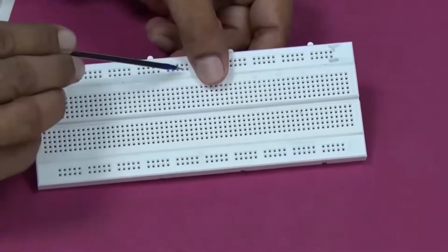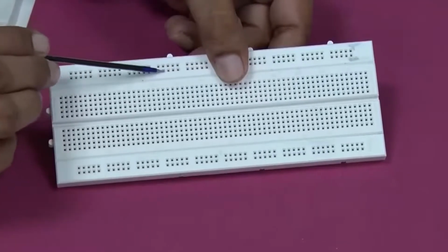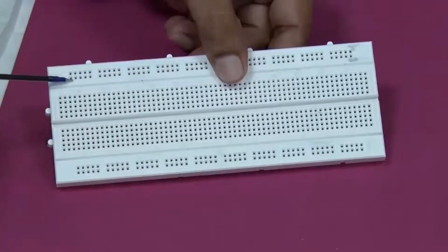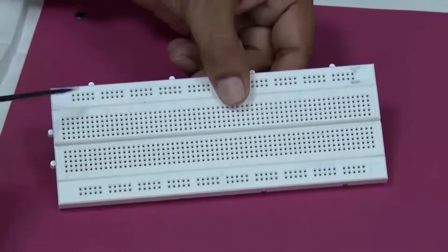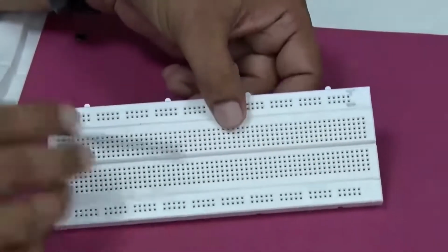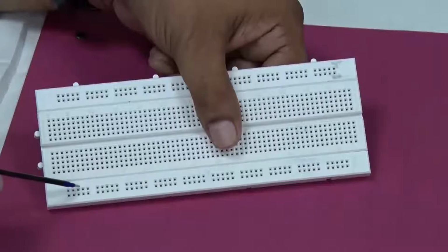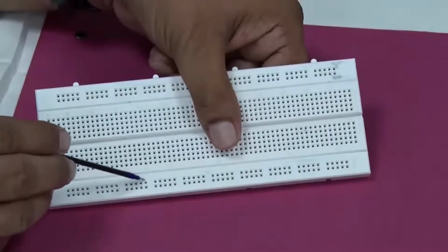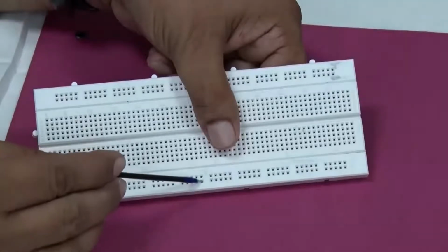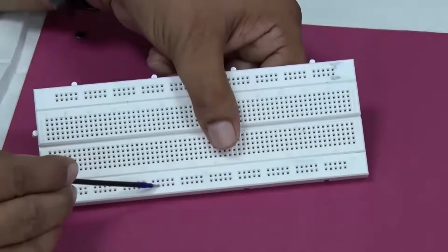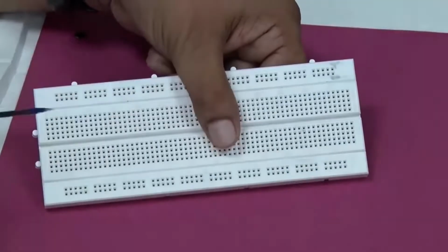Similarly, if you go to this next line, there are 25 holes there, 5 here, then 5 here, and so on. All these 25 are internally connected to each other. And similarly is the story on the other side, and similar is the story on the bottom side. Here also all these holes are internally connected on one longer line. On the bottommost line also, all these 25 are internally connected to each other. That is it. And similarly for this side.